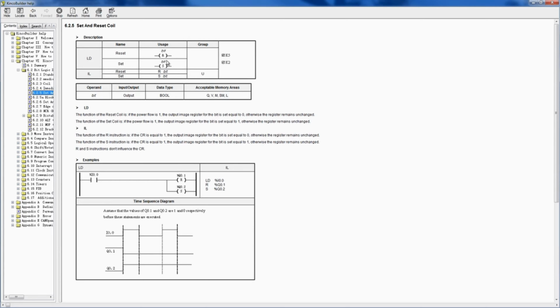So this Q output could be set by something. Let's say you're running to a position, you say, oh, I want this to be triggered when I have this immediate switch, something that's not a throwing switch where it has a couple of state settings, but it's just like a push button. Say you want a push button to start the operation and a push button to end the operation. So that push button where it presses once is instantaneous and goes back to its standard state, spring reset.